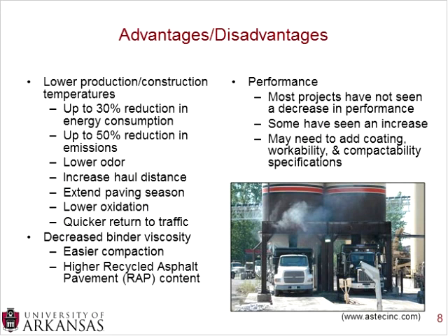Now here's a long laundry list of advantages and disadvantages. You have your lower production and construction temperatures, and with those, you get reduction in energy, reduction in emission, reduction in odor, and oxidation. All of these are advantages to those lower temperatures.